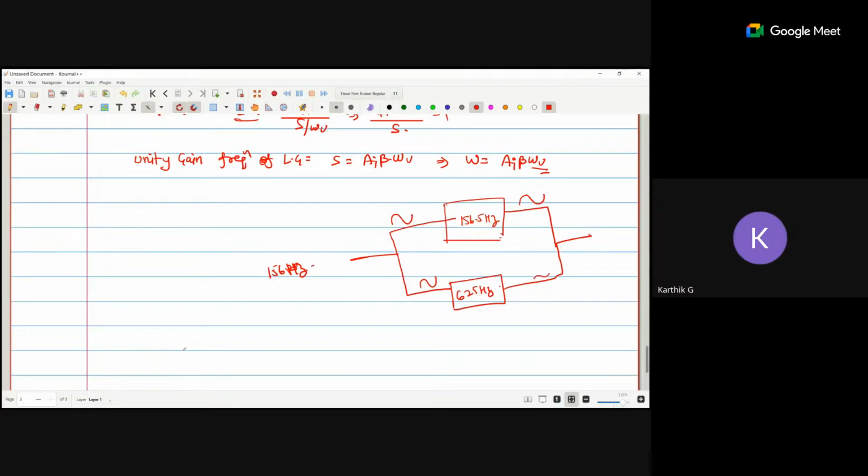Because I have used different capacitors and resistors, so the sine wave looks like a square wave. Is that fine? The sine wave looks like a square wave. Is it input or output? You are asking input or output, sir. Output. Just change the frequencies, particularly the resistor and capacitor, and that will be an accurately sinusoidal signal. Why are you getting the square wave at the output?